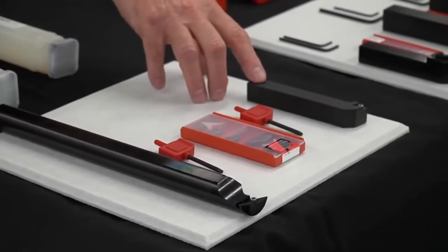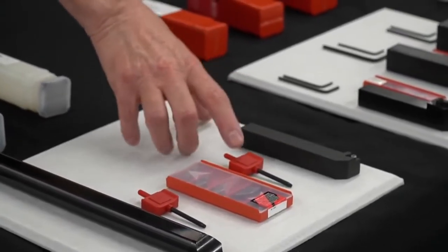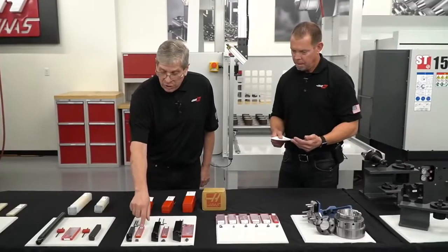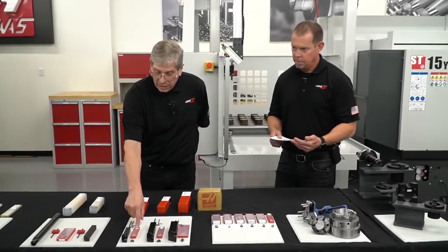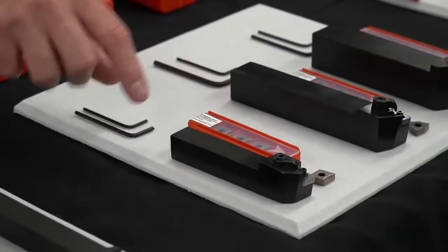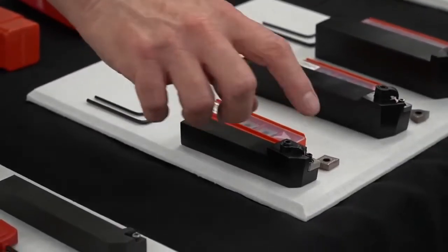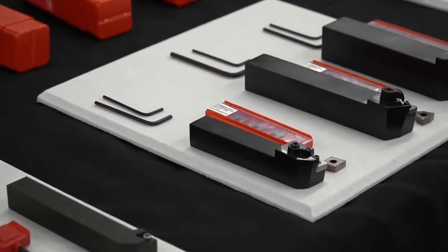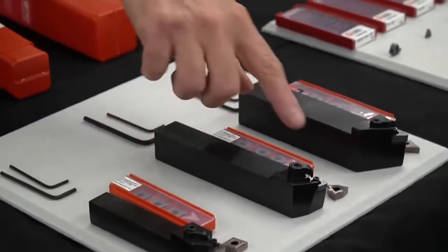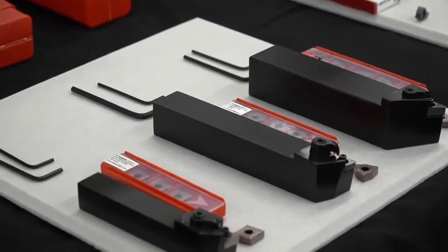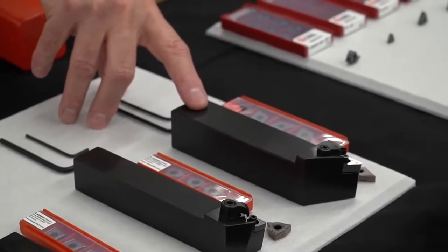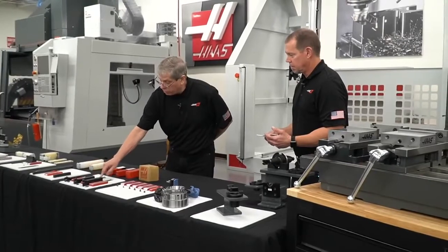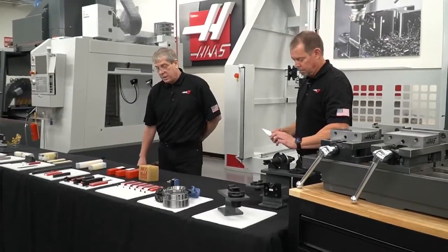I've got a smaller CNMG tool holder. Again, that tool holder comes with the Torx wrench. And then next size over, CNMG 432, your basic workhorse in turning. Each of these tool holders with the top clamp style come with the 2 hex keys needed to install those inserts. Here's the larger 1-inch tool holder with the trigon style insert. The next one is the 55-degree diamond tool holder in the 1.25" size for your larger machines. Again, they all come with the hex keys.